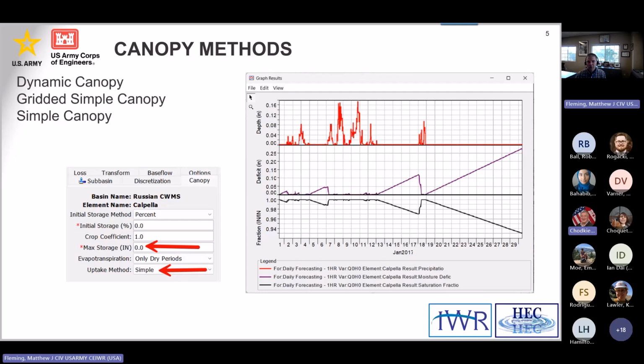What you can do is do some kind of correlation analysis between what's measured in the field, and if you had a long-term continuous simulation in HMS and the times overlapped, right? You would just go to your HMS model and pick off, this is what HMS estimated or computed for that time that soil moisture gauge recorded something, right? And so you have that correlation done, and then in the future, whenever you're doing a flood forecast, you would look at, well, this is the soil moisture gauge now, and use that analysis to help inform you what a good initial deficit is going to be.